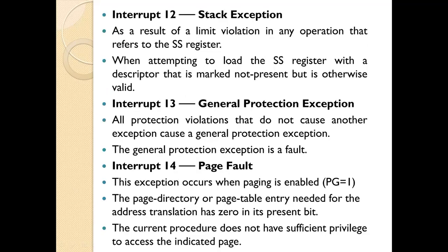Interrupt 12, stack exception, occurs as a result of a limit violation in any operation that refers to the stack segment registers, or when attempting to load the stack segment register with a descriptor that is marked not present but is otherwise valid. Interrupt 13, general protection exception. A protection violation that does not cause another exception causes a general protection exception. The general protection exception is a fault.